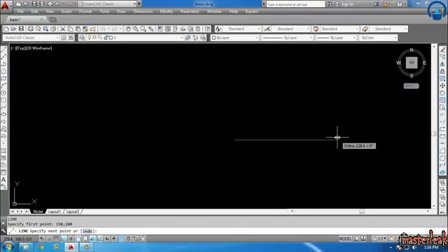Here you want to draw a square with dimension 50 by 50. So your next coordinates will be 150,150. Then on specify next point, type 100,150. Enter. On next point, 100,100.